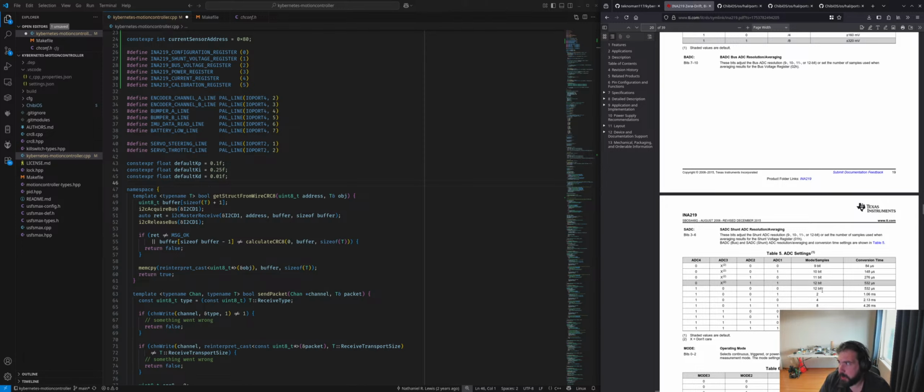So if you really want a low resolution, very rough but very immediate measurement, 84 microseconds, you can do a 9-bit sampling of either the shunt register or the bus voltage. But if you're willing to wait longer, it can run with more precision, going from 532 microseconds to 1.06 milliseconds. So what it's probably doing is taking two 12-bit values and averaging them. This is still very quick.